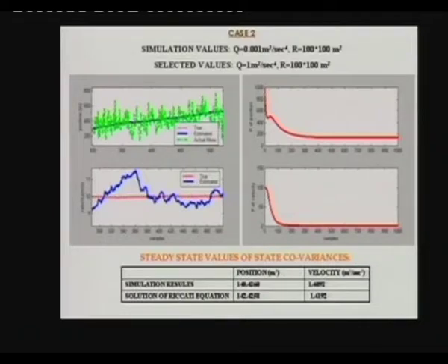So the effect of that much high increase on the true acceleration is not that high, because after all signals are zero mean. So when you doubly integrate, the position signal is not that much affected, and the measurement noise is at the same level, right? So therefore the position data looks very similar.